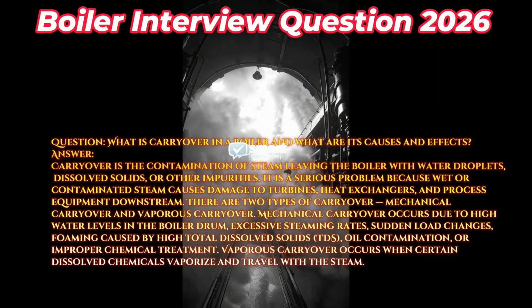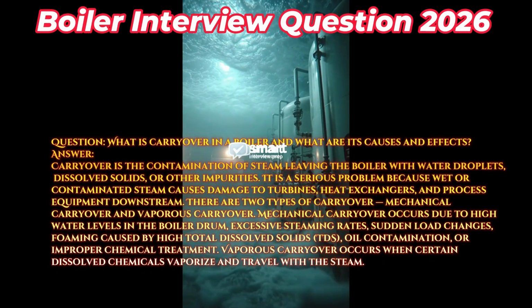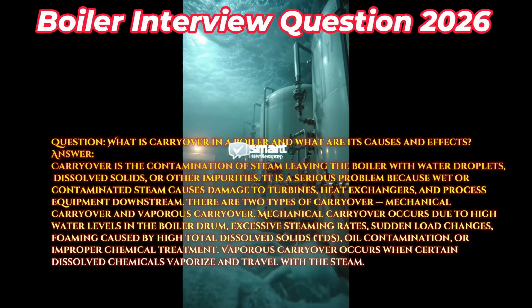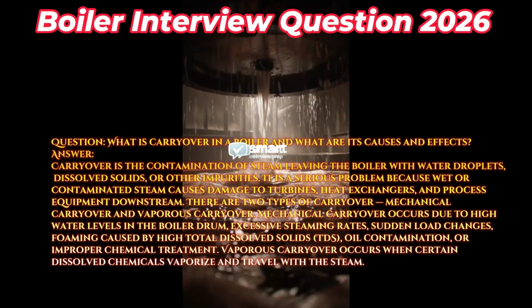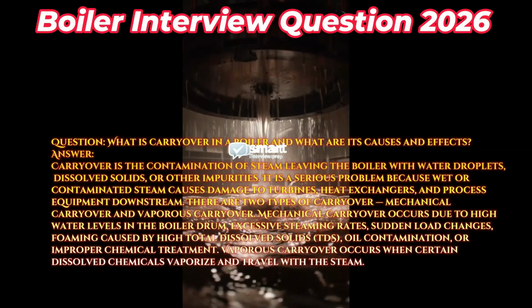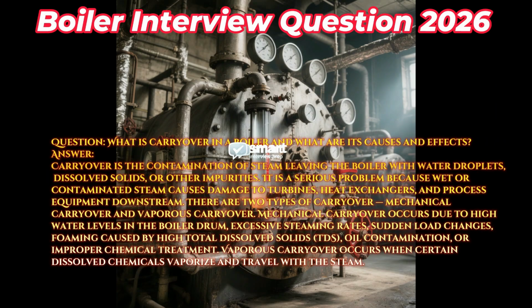Mechanical carryover occurs due to high water levels in the boiler drum, excessive steaming rates, sudden load changes, foaming caused by high total dissolved solids, TDS, oil contamination, or improper chemical treatment. Vaporous carryover occurs when certain dissolved chemicals vaporize and travel with the steam.